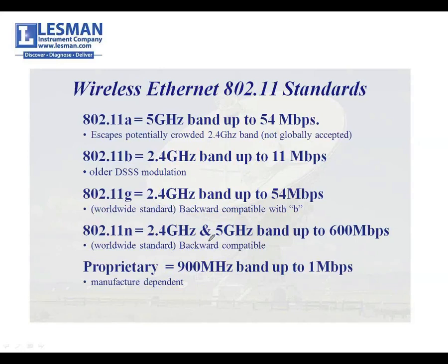One thing I'd like you to notice down at the bottom here, here's our 900 megahertz band, which is our bullet, which we can shoot far and shoot through lots of walls, and we can actually send Ethernet via this 900 megahertz band. Now, it's not very fast. It's only 1 megabit, so you couldn't do video, but you could easily service quite a bit of I/O, remote I/O, or something else that needed to move quickly.